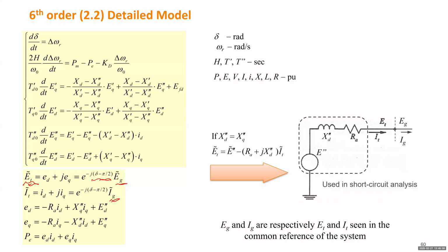First, okay, so we have four equations, right? They categorize the four flux linkage state variables. Those two are transient dynamic, so we need to keep those two, at least, because when we see the 2.1 model, we have two state variables in the D axis and one state variable in the Q axis. So this is D, this is Q.